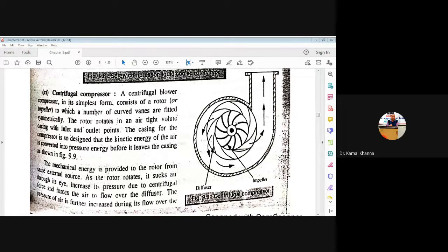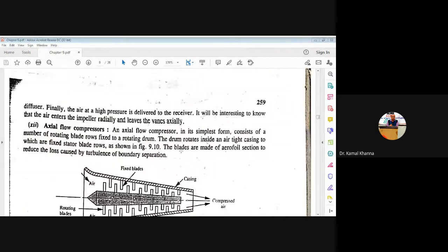The direction of the vanes of the diffuser and the impeller are opposite, so that more pressure energy is generated within the air, and the air is compressed to some extent so that its pressure is increased. So here we are increasing the pressure of the air only with the help of the centrifugal force. As soon as the desired amount of pressure has been reached in the compressed air, it is supplied to the other components of the pneumatic systems.